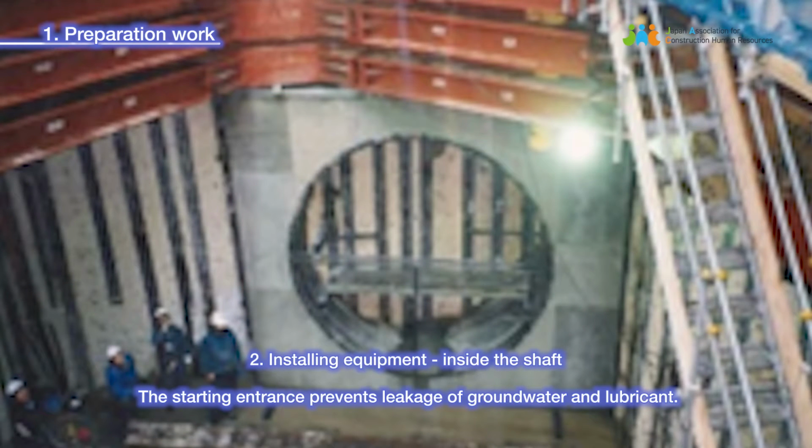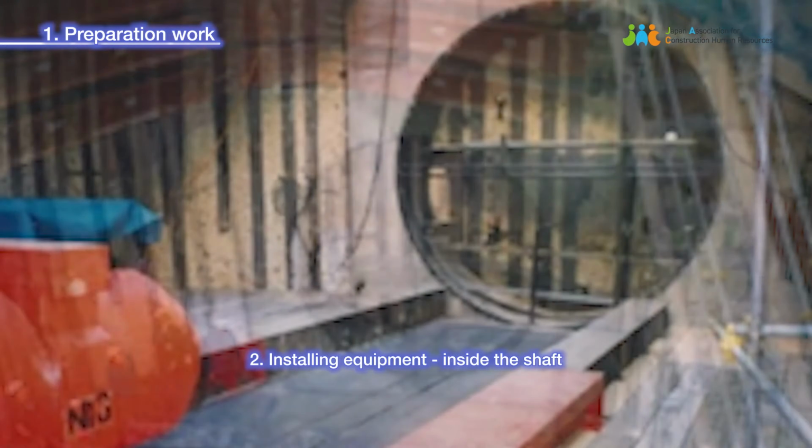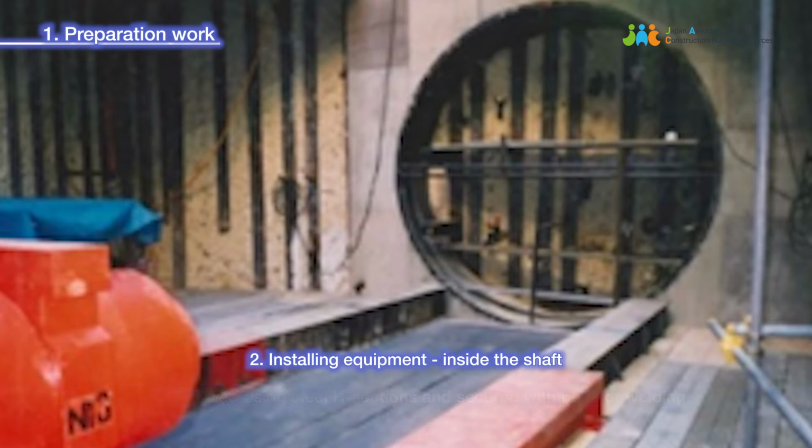The starting entrance prevents leakage of groundwater and lubricant. The water stop ring is welded to the retainer, and concrete is poured using formwork to construct the structure. The pipe jacking stage is installed firmly and stably, with the specified height, slope, and direction of excavation. It is assembled using steel H-sections and secured with bolts or welding.